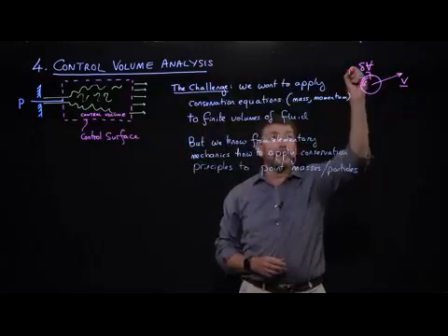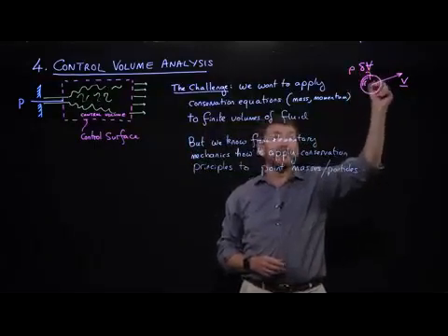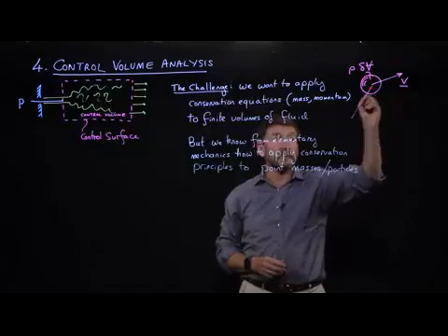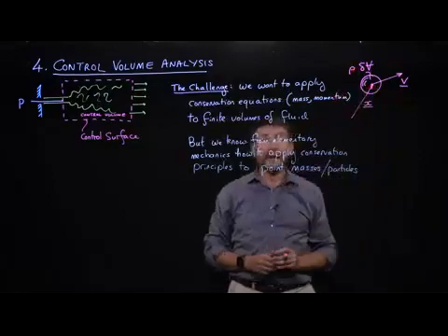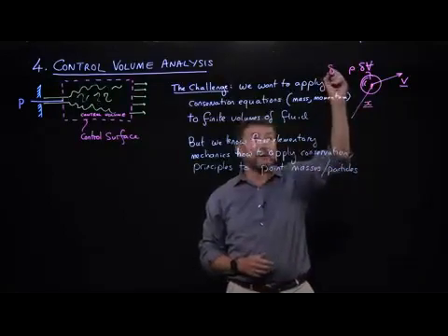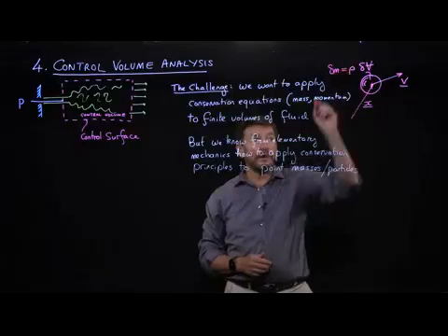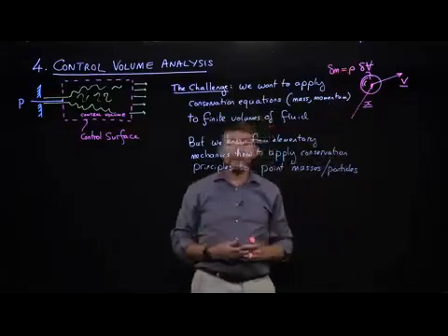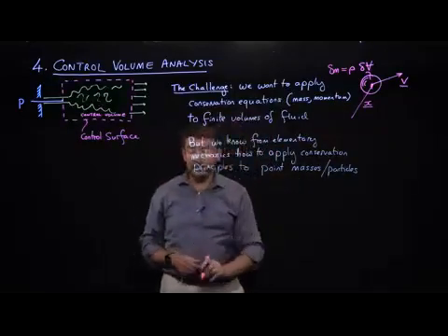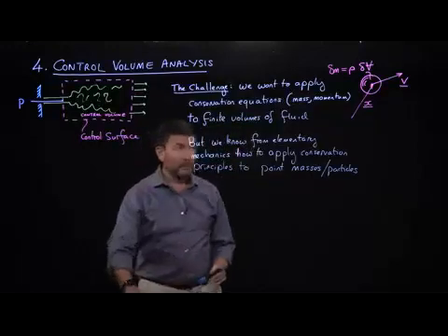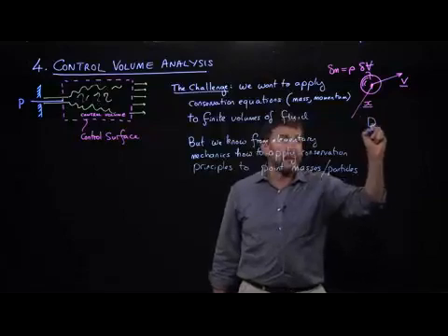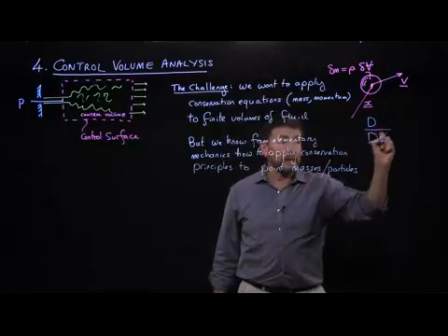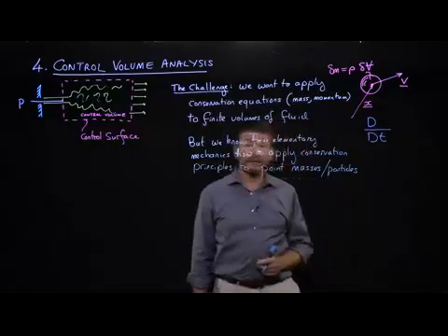So our point mass here might have a density, which is a function of spatial position. So this might be at a position x. And our point mass might be moving through it, and it might have a density there. And so we might know how to apply equations that conserve either mass or momentum or energy on our little point mass like this. So, for example, we might write down a statement of conservation of mass that says something about the time derivative following a material element.